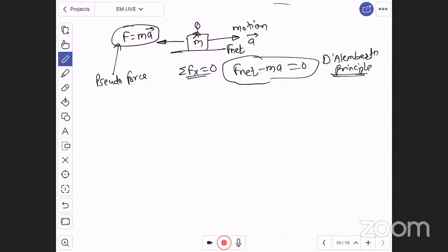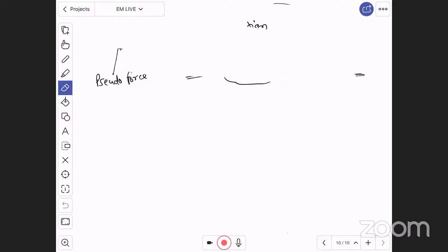Newton's force was different, D'Alembert's force is different, right. D'Alembert's force is opposite to Newton's force. As per Newton's force, the object is moving in the direction of force, and this is the inertia force. Therefore inertia force is always in the direction opposite to the motion, and if I apply this inertia force on the object, it will come to rest, and we can use equilibrium equations. Right. Now with this concept, pseudo force concept, let us solve this question.